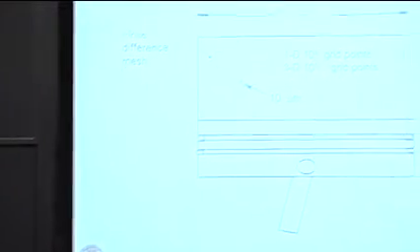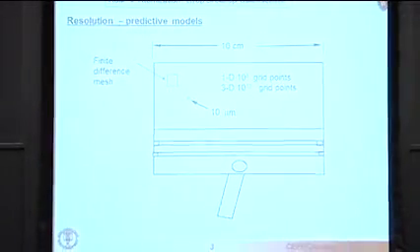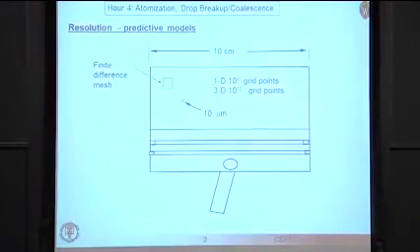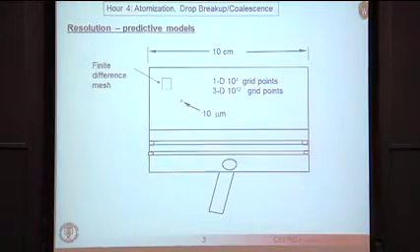Okay, so as I say, today will be quite heavily focused on modeling details. So if you look at an internal combustion engine, I've just drawn a typical truck engine here where the bore is about 10 centimeters in diameter. And of course, we have direct injection of a spray. The spray droplets may be characterized by sizes on the order of 10 microns or so.